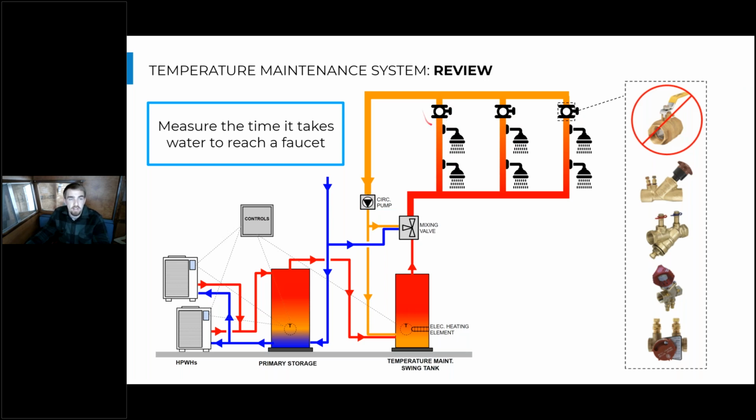Right, so we have balancing valves on each segment of this loop so we can balance out those flows. And it's really important in the design process and the verification installation process that these aren't just basically ball valves that are throttled down to accommodate that flow. Ball valves are meant to be fully open or fully closed, so they don't reliably restrict flow in the way that a balancing valve is designed to do.